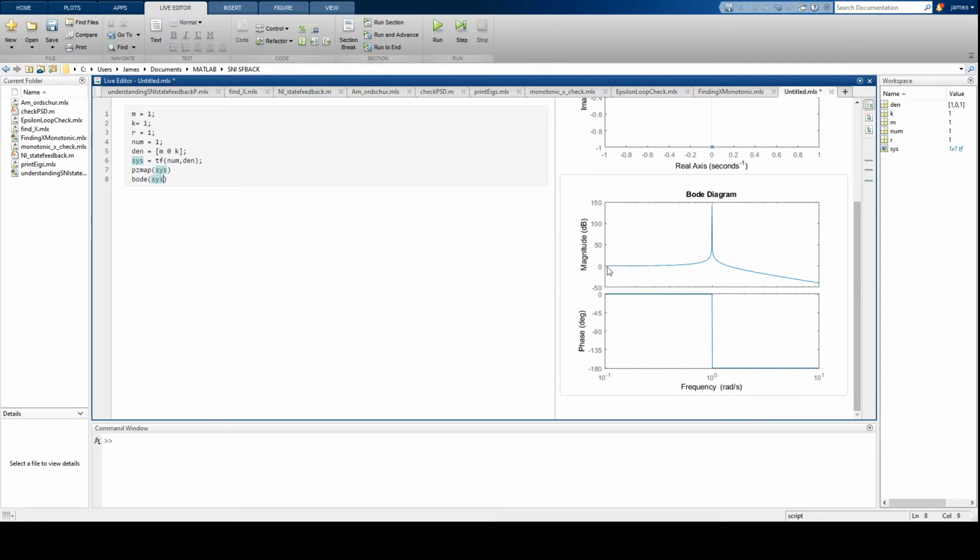And what you see is the response pretty much sits at roughly our 1 where we started off, because remember this is in dB, so 0 dB is equivalent to our 1. And we come across here and see it's relatively flat, and then at this frequency here, we get this massive spike in the gain, and then we start to see that roll-off we described. So this is kind of like that low-pass filter, except we have this huge spike. Where does that spike come from? Why is that happening? We did not see that with our first-order systems. So let's cut back across, and let's see if we can figure out what this spike is.